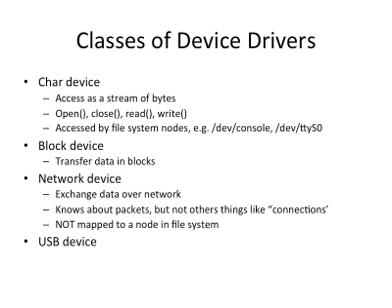There are different classes of device drivers. Character devices are designed to access a stream of bytes, and should have minimally these functions: open, close, read, and write. There are many device drivers that belong to this category, for example, console or ttyS0.